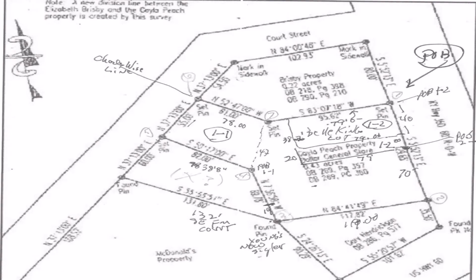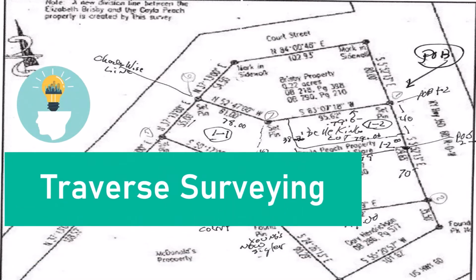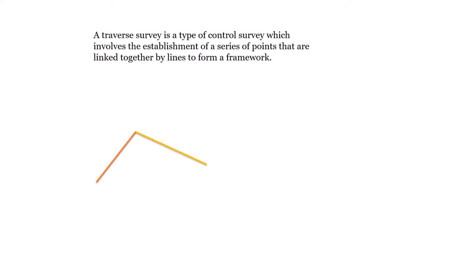A traverse survey is a type of control survey which involves the establishment of a series of points that are linked together by lines to form a framework. The series of straight lines that connect the successive points are called traverse lines. The ends that define each traverse line are called traverse stations or traverse points. The framework formed by connecting survey lines of known length and direction is called a traverse.